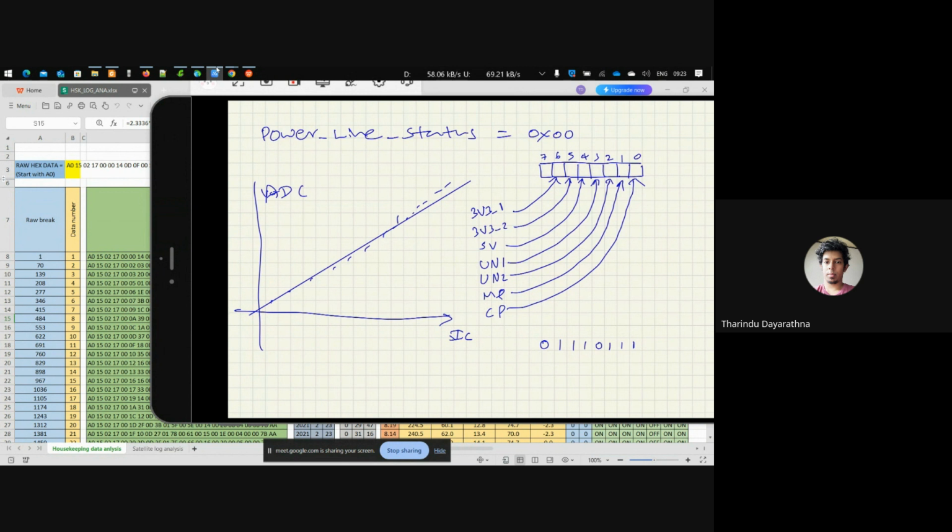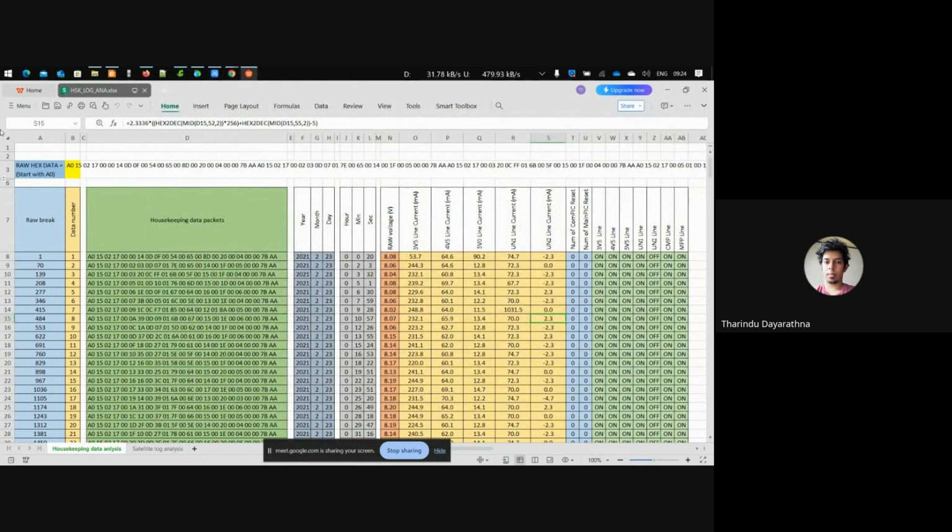So let's say if you measure a small voltage, maybe that ADC value is 5 or something. It can be 6 or it can be 4 because of noise. That error can happen even in your reading. So you have to understand there is always an error. The thing is, you have to minimize that error and you have to accept whether it's okay or not.